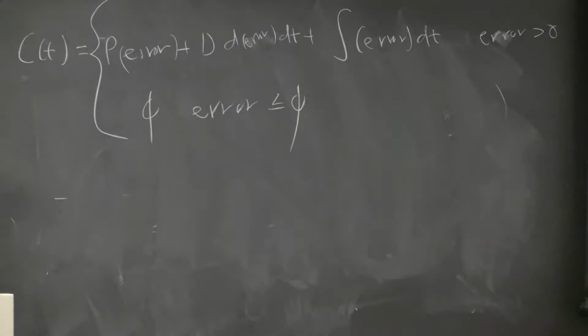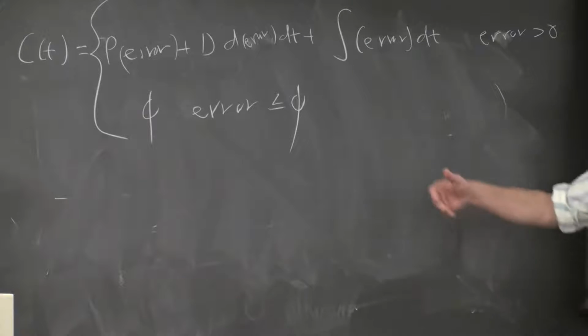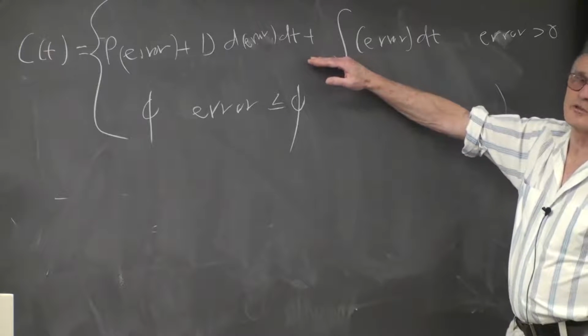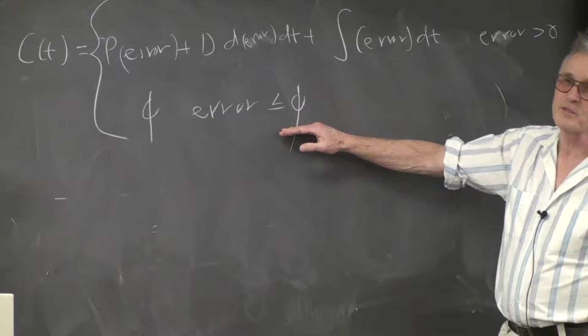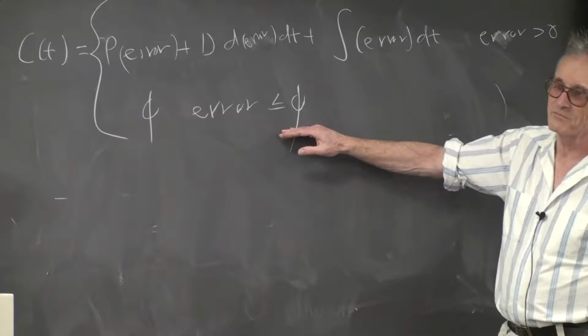That says we can't slow the motor down actively. We just have to let it slow down because it has friction. So the system is a second order system when it's under drive, and it's a first order system when it's not under drive. It is piecewise linear.